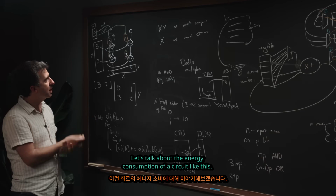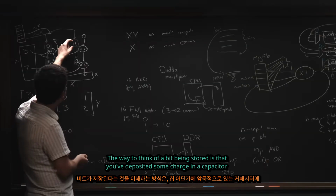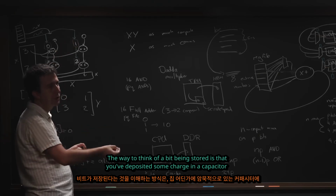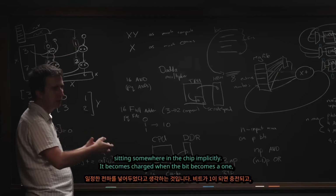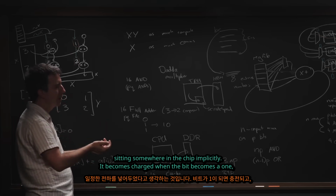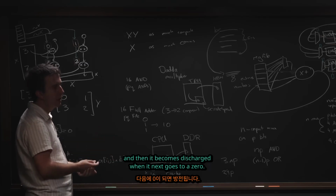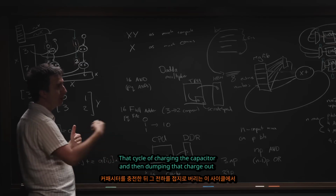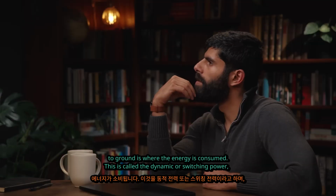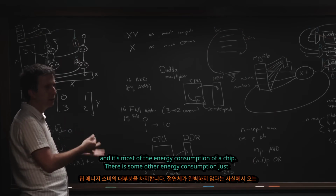So actually, let's talk about the energy consumption of a circuit like this. The way to think of a bit being stored is you've actually deposited some charge in a capacitor somewhere in the chip implicitly. So it becomes charged when it becomes a 1, and then it becomes discharged when it next goes to a 0. And that cycle of charging the capacitor and then dumping that charge out to ground, that is where the energy is consumed. Yeah. This is called the dynamic or switching power. This is most of the energy consumption of a chip.